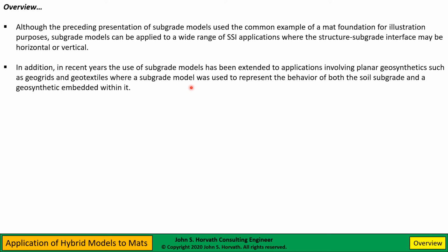So the point I'm getting at is, although I used a mat foundation to illustrate subgrade models, these subgrade models can be used in a very wide variety of problems. Like I indicated earlier on in that Army Corps of Engineers publication from the 1990s, they showed how to use the beam column solution for a beam on a subgrade, for a laterally loaded pile, and for an anchored bulkhead.